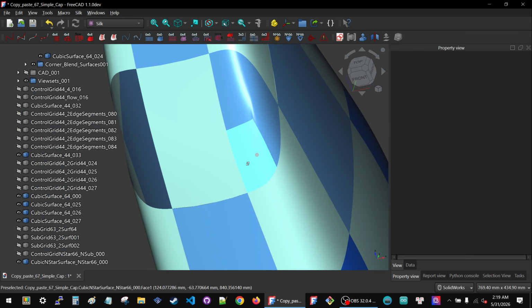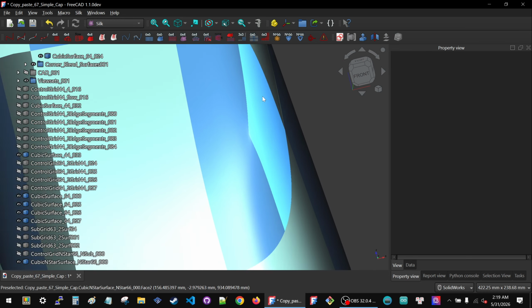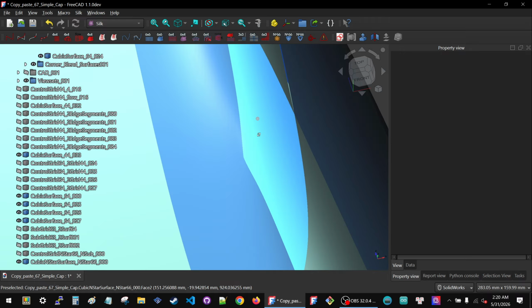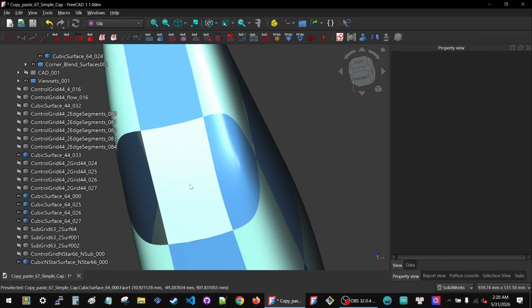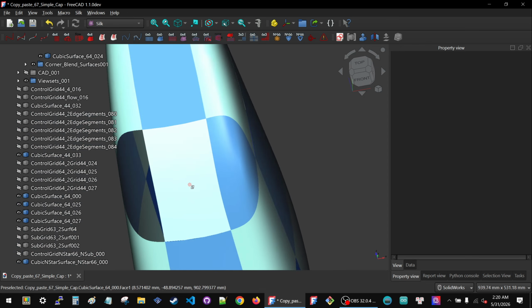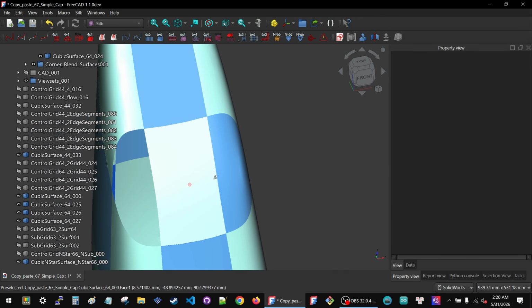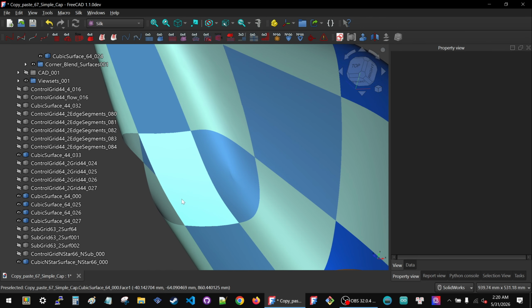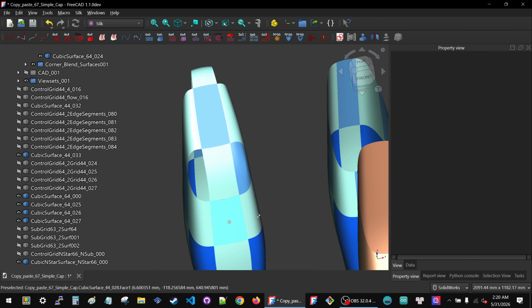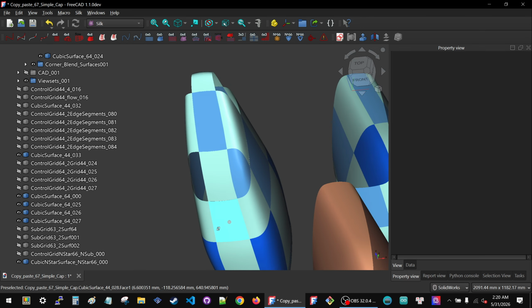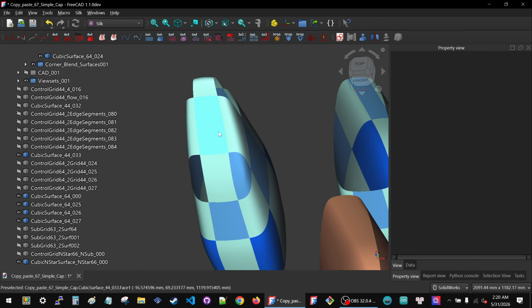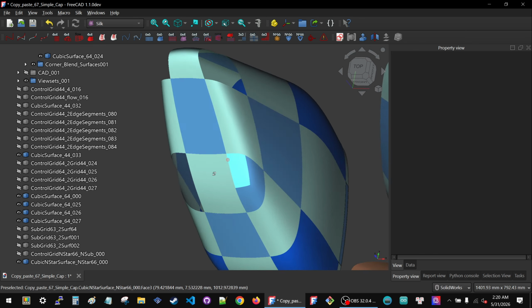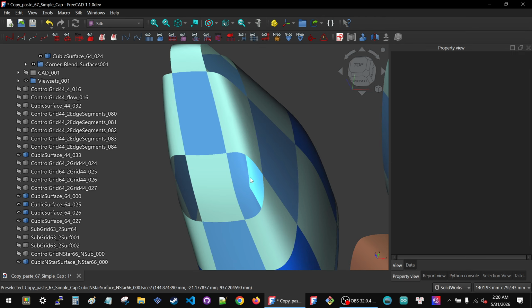Okay, it's a little bit better, but you can still see the defect. Remember that we can improve this defect later. And the nice thing about this is that it's really fast. It computes really fast, it has a fixed size, and it's very stable, unlike the FreeCAD surface workbench fill. So this is a good first step to use. And what we're going to do after we make all 4 is we will do a 3D sculpt on this thing. After we do the 3D sculpting on this face, then we'll come back and see what we can do to make this surface better.